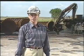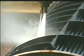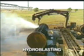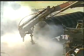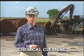After fouling has occurred, removal methods depend on the type and severity of the deposits. Deposits on the outside of tubes can often be removed by hydroblasting, a high-pressure stream of water that loosens and washes away the deposits. Streams of water or steam can also move the deposits from the inside of a tube. If water and steam fail, chemical cleaning may dissolve the deposits.